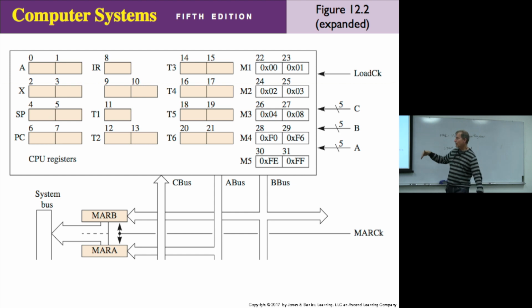So now, when we add 1 to the program counter, we'll have to add the low order byte of the program counter to, now is there a 1 up here? Is there a constant 1 in this register bank? Yes, number 23 is 1. Does everybody see that? That's a read-only memory 1. So to add 1 to the program counter, we'll take the program counter, the least significant byte, which is register 7 in the bank, and 23, which is the 1, and we'll add them.